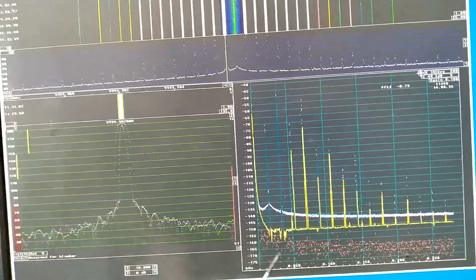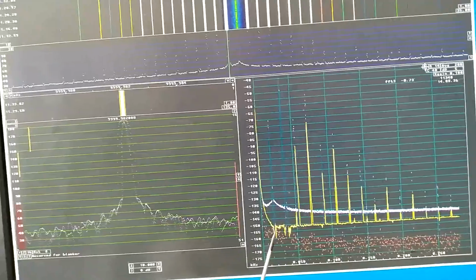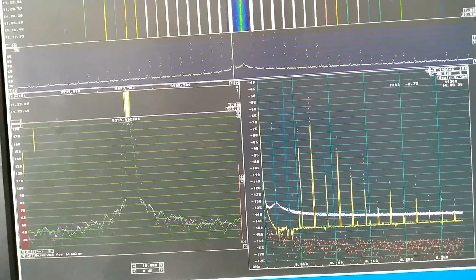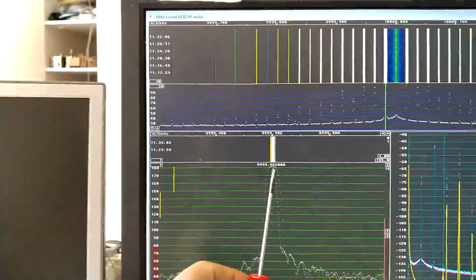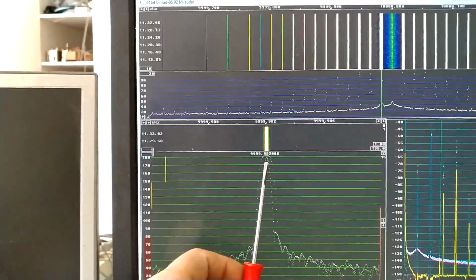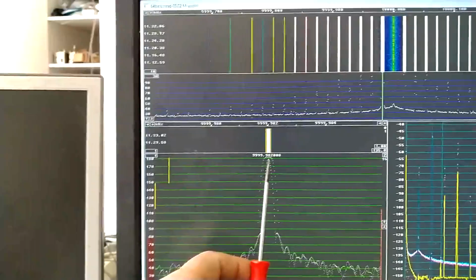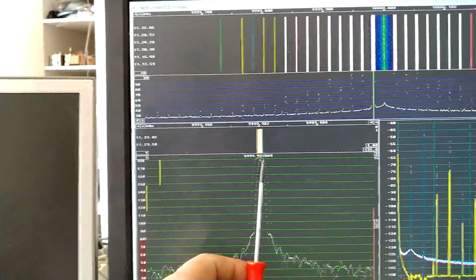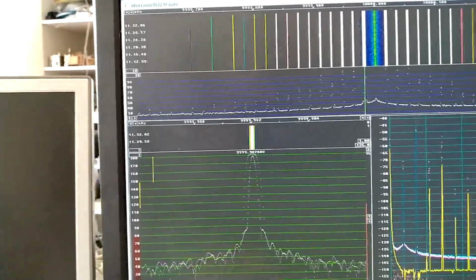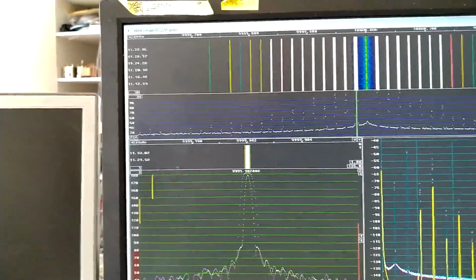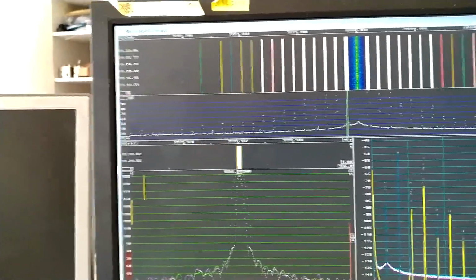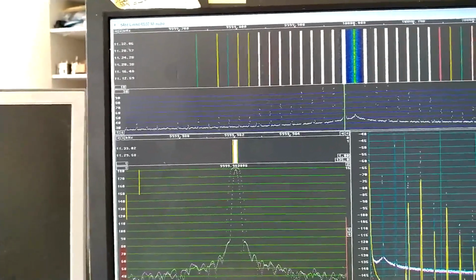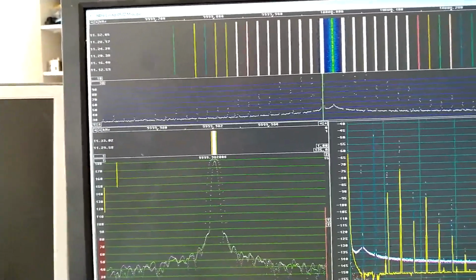And I think the phase angle that comes here depends on how well centered the signal is in the filter. Because the phase of the carrier will change a little bit depending on where in the filter the carrier is, while the second harmonic will not change phase when the frequency is shifted a little bit.